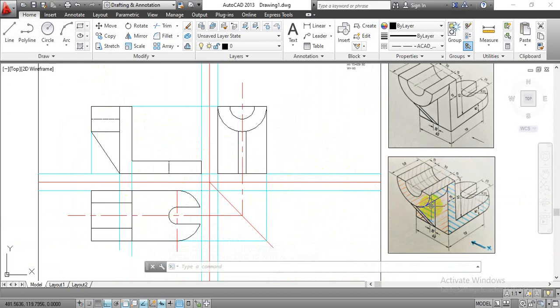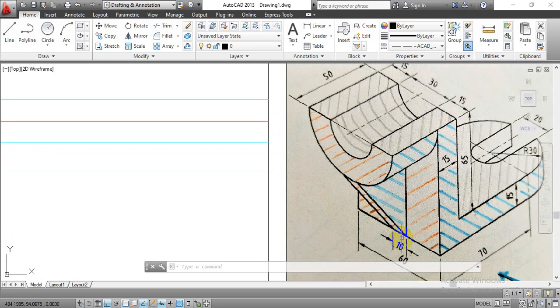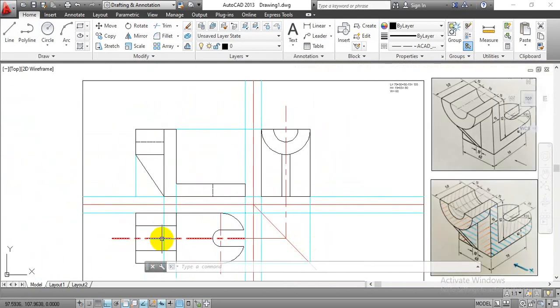to draw the hidden surfaces in a top view as well. So in a top view projection, we are unable to see this rib section while looking from the top end. To that, we have to show two dotted lines for the width equal to 10 mm. Okay, so that we can draw with respect to this center line. We have to take 5 mm, 5 mm distance on either side, and that we are going to complete from this point to this point. Okay, so we have starting point over here and the end point over here. So it will cover only this much distance linearly.